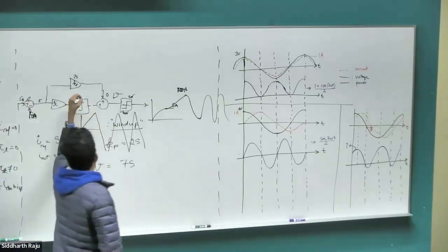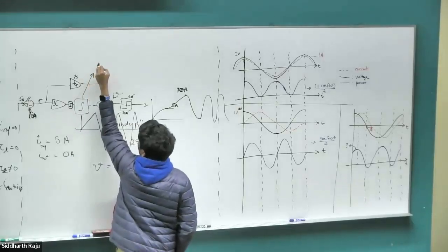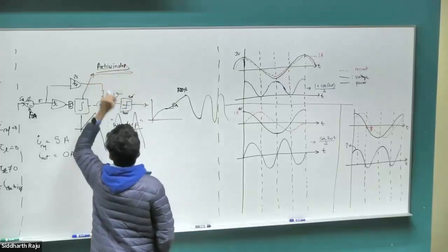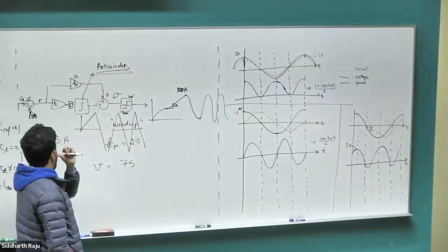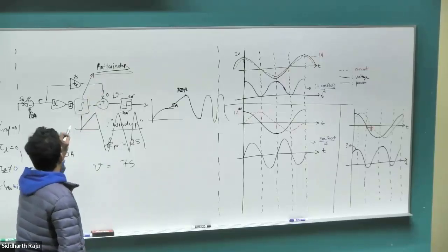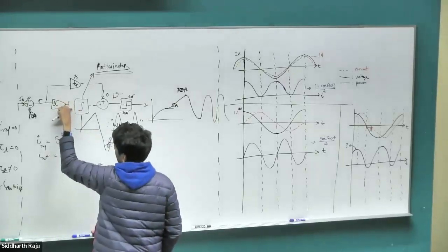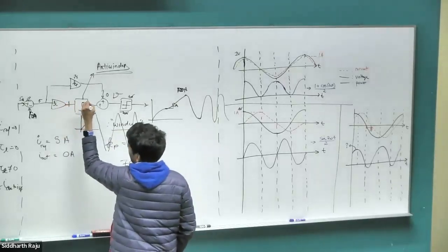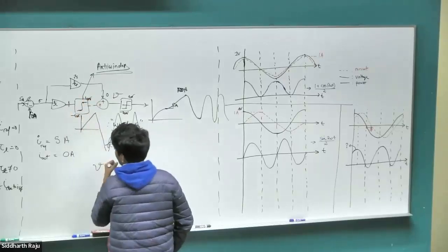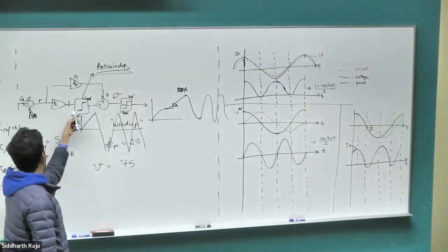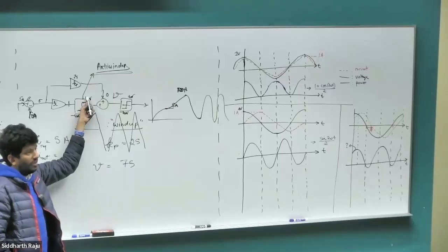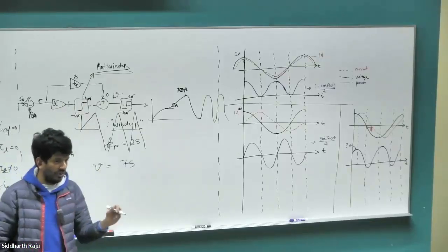So in MATLAB, if you look at integrators, there's an option called anti-windup. Or even in the lab, when you do the hardware portion of the experiment on week 3 of a project, we will set this anti-windup turned on. So what it does is, you can set the anti-windup limit, same as saturation, but it does a little bit more complicated. So let's say I set the upper limit for the anti-windup at 40, lower limit at -40. So what it'll do is after the output of the integrator has reached 40 volts, no matter what the input is, it'll stop integrating. It just won't do any work after that.